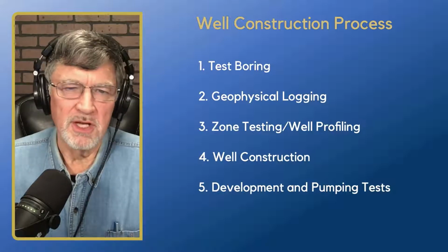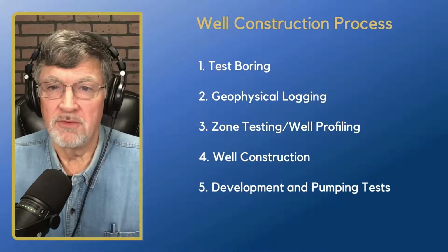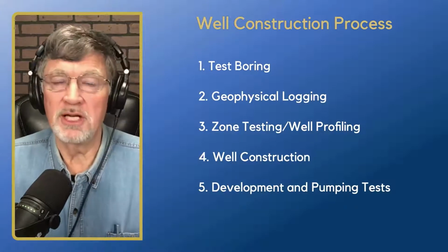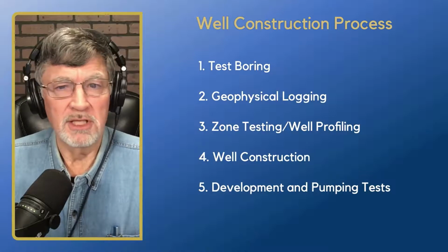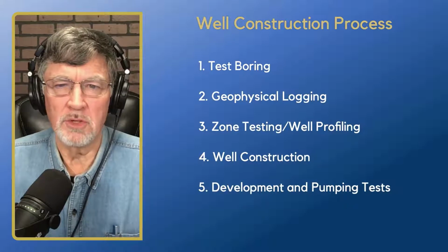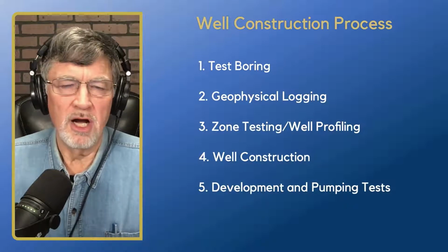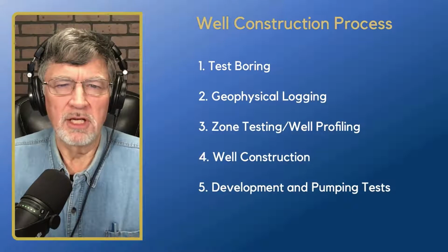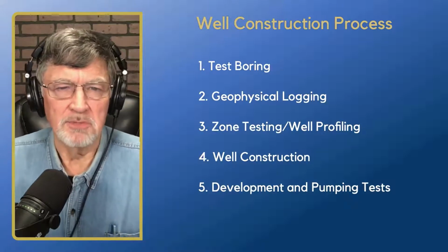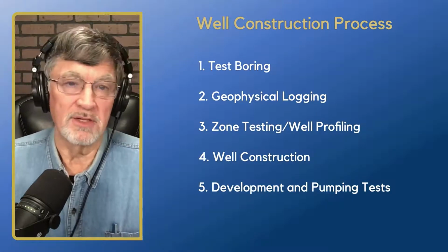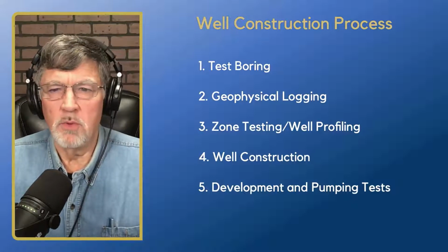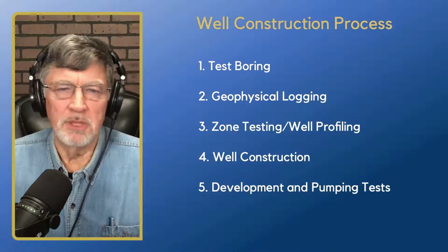Once our test boring is done, we're going to do our geophysical logging. I also highly recommend doing geologic logging during the drilling of the test boring, and then after the test boring is done, going in and doing geophysical logging. We'll take our geophysical logs and our geologic logs, and then we're going to do some zone testing or well profiling, as the case may be. We'll look at the alternatives here today. That's the topic of our show. Then based on that information, we're going to do well construction, and then finally on to development and pumping tests.